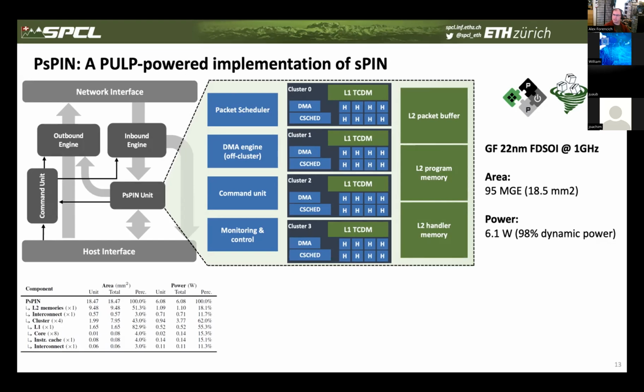And what clock frequency are you running at? Is all this running at 250 synchronous? No. This is the current culprit. It's running at 40 MHz. The reason is that this core is really tuned for ASIC. It doesn't have any kind of design for FPGAs, for example pipelining or anything like that.